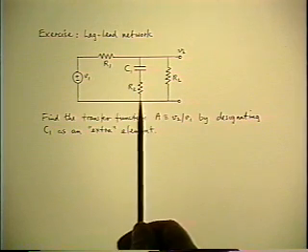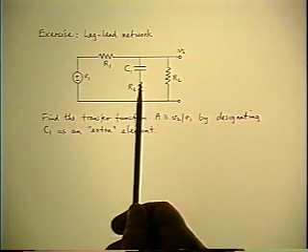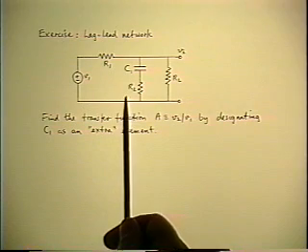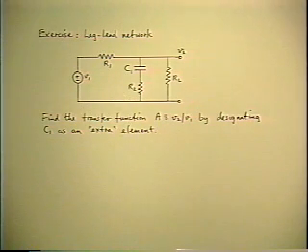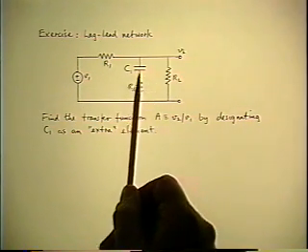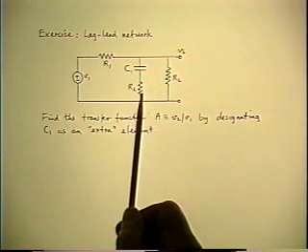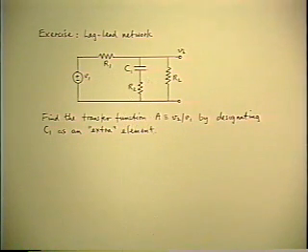Well, since the previous time we did this, we had the zero frequency gain as reference to start with. Let's adopt the same reference this time, which means that when you designate C1 as extra and throw it away, replace it with an open. And that's the only choice that's left, and the rest of it is simply calculating the reference gain and the two driving point resistances.